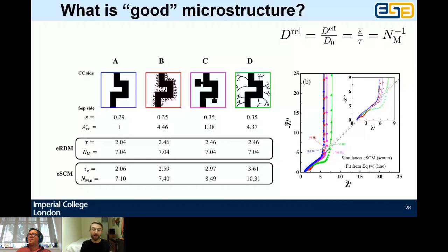Electrode thickness. Well, again, the scaling of your pore feature size relative to your electrode thickness, and how your straight pipe pores would compare to the available surface area perhaps near the separator, these things will all scale. It is fundamentally a non-dimensional parameter, but I suspect as your electrode gets thicker, the impact of your tortuosity factor will be more pronounced because you're having a hard time going through a longer volume.